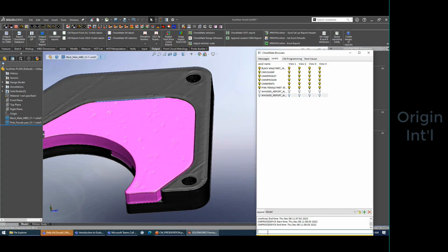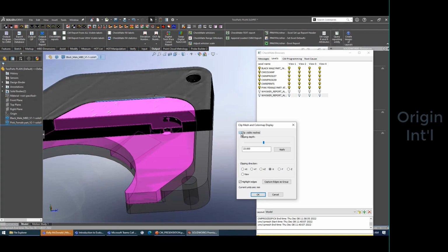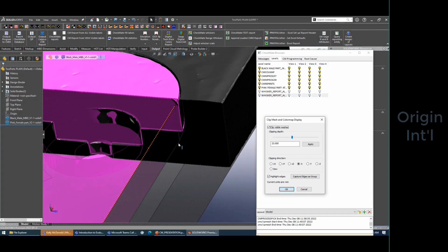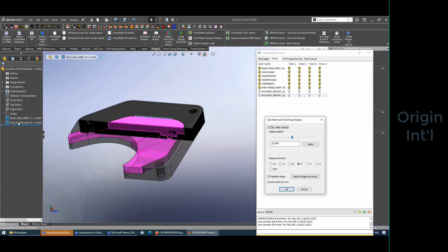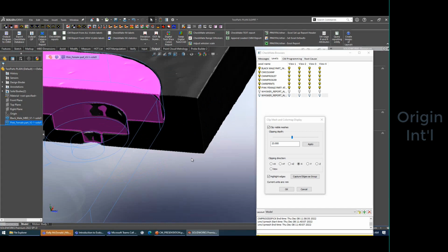But there's a really cool new addition that I'm going to show now, which is the ability to walk through the mesh. I've got two meshes that are aligned with each other. So this is a really nice way to tell, do these parts go together? I'm going to say clip, and you can see that I already had one before. I've obviously worked with this file before, so it remembered the 23 value. You can see it's doing a CAD cross section. I hate to oversimplify it that way, but you're not dealing from a CAD point of view. You're actually doing it from a functional mating and sectioning both parts at the same time.